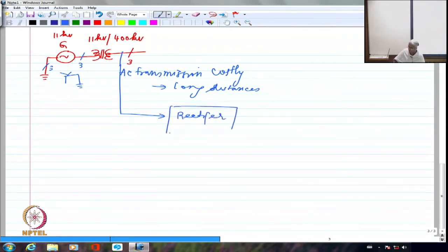And the rectifier obviously has to withstand 400 multiplied by √2 kV, because 400 kV is RMS. So each of the devices has to withstand 400 times √2, and I have to put in a factor of safety, in all probability 1.25 or 1.2, so it is going to be way too high. There are no devices available for 400 kV multiplied by √2 multiplied by 1.2 or whatever. That's not going to be possible.